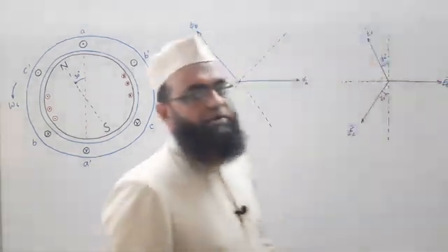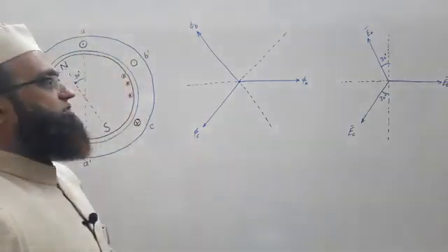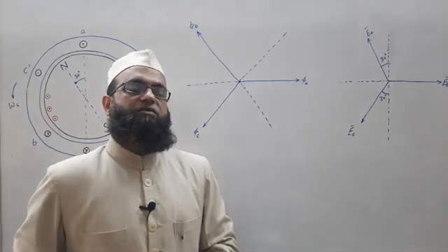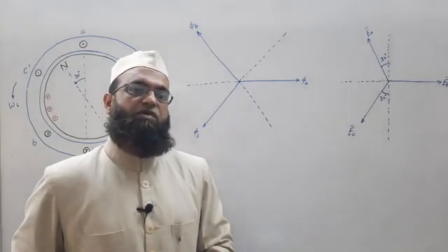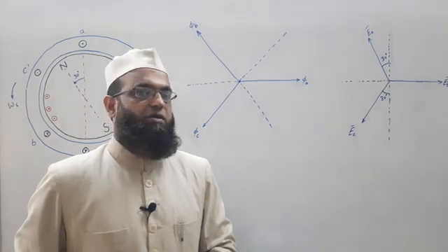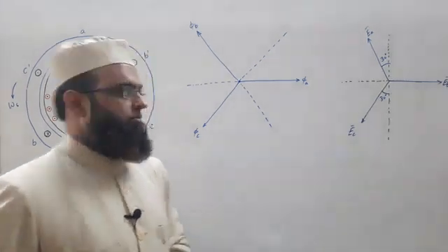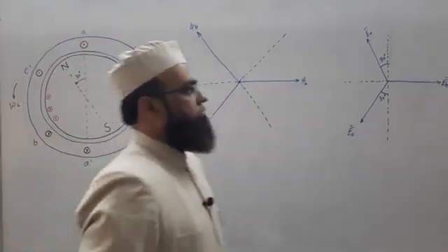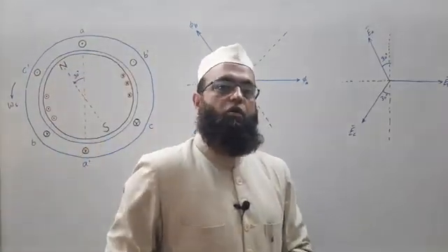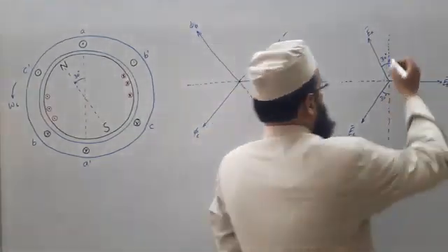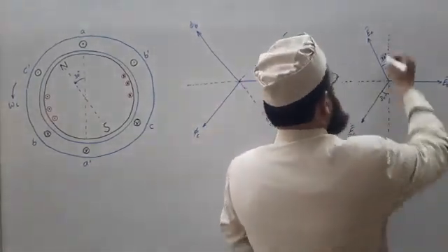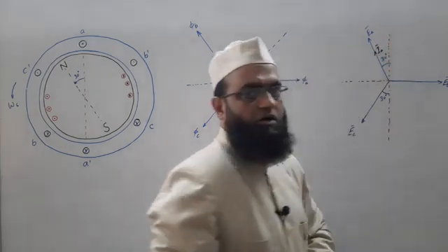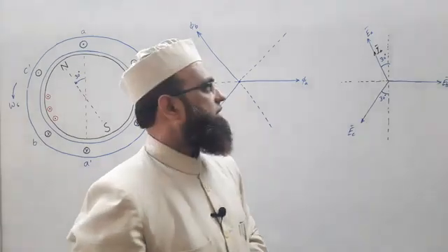So, for that, start a similar procedure. What was that? First we will write the corresponding phase currents and corresponding fluxes and the resultant of armature flux, and compare with the main field flux. So, this time the main field flux is having direction this way, whatever it is having. So, for a unity power factor load, wherever EMF will be there, current will be there in the same phase, IA, that is, the power factor angle is 0.